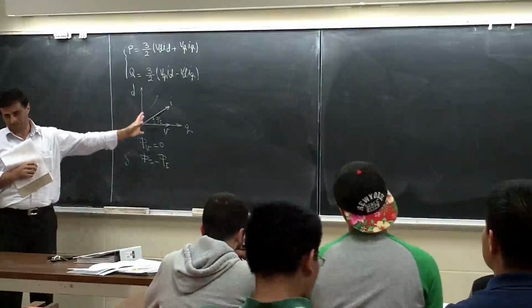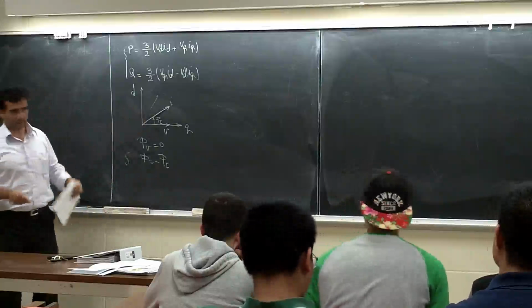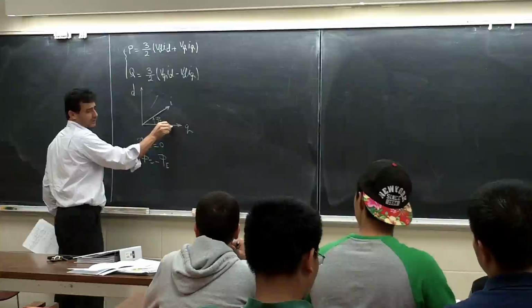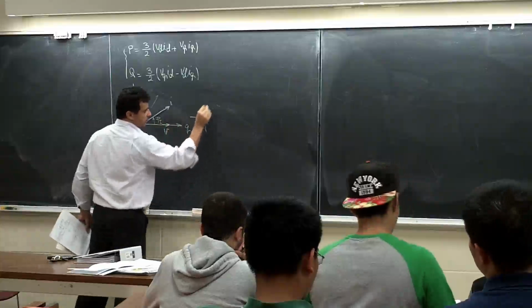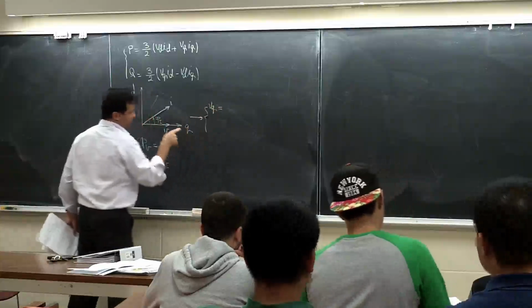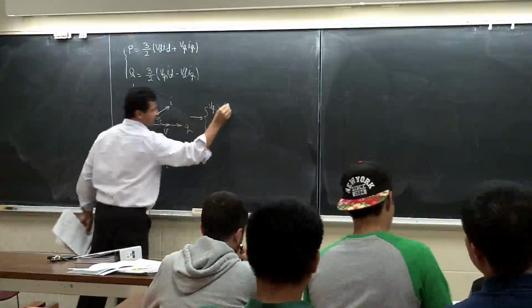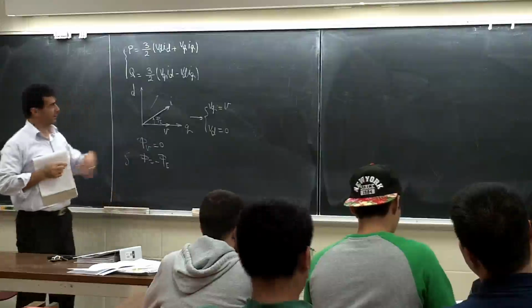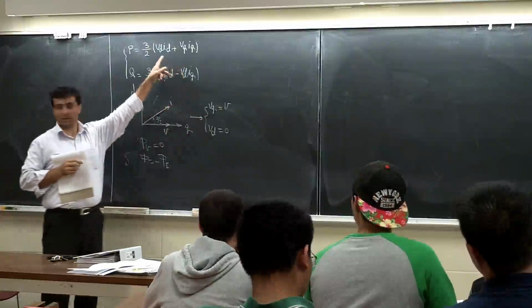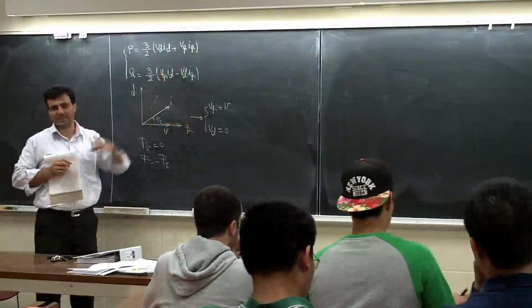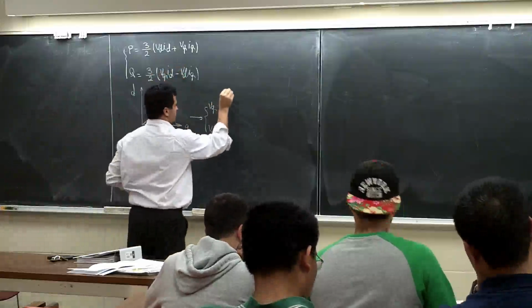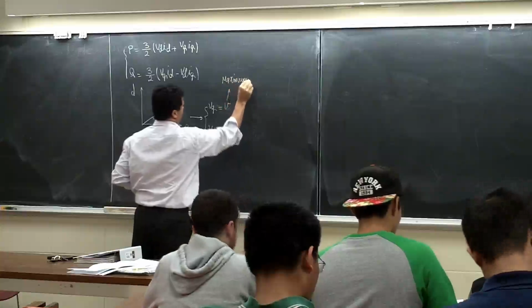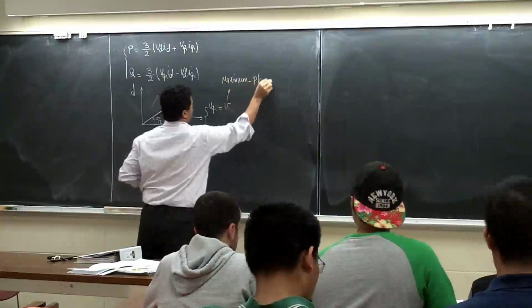Now if we have this, what was the result? If I project this on the Q axis, how much is the VQ? VQ is V. And how much is the VD? 0, right? So basically we place these two values in this equation, and V is the maximum phase voltage.